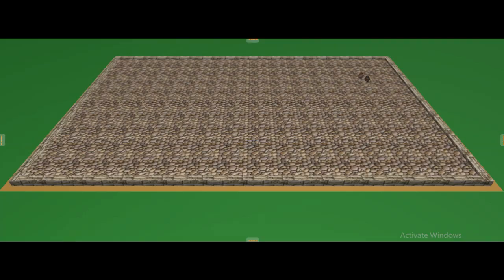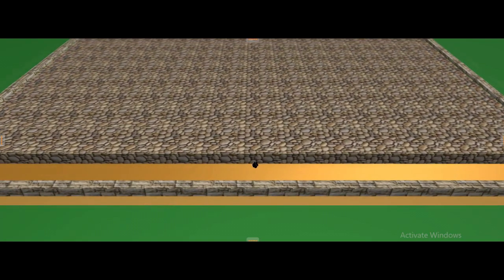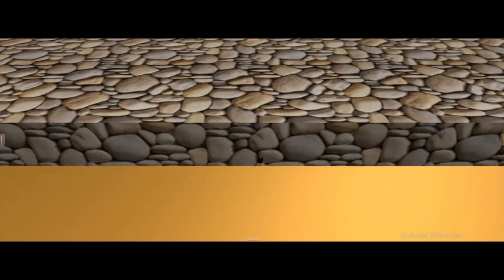So by demonstration, the whole of this surface has been covered by the hardcore. Remember, I'm using the interior corner to interior corner to be 11.60 meters. Likewise, for the width, I'm using the interior dimension from this interior corner to this interior corner to be 7.60. So when I have to square this one, I multiply those two figures by the thickness, and the thickness of this hardcore is 310 from our previous takeoff. Let me give you close range: that thickness is from this upper edge to this lower edge.